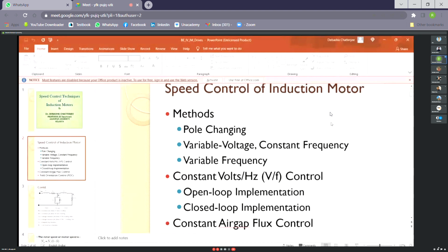So the major cause we are finding here is the change in flux linkage in the rotor conductors. That is actually causing the rotation, right? And in other words, the rotor conductors try to catch the stator magnetic field in speed, so that there is no change in flux linkage. That means the rotation will be in the direction of the stator magnetic field, or air gap magnetic field, whatever it is.